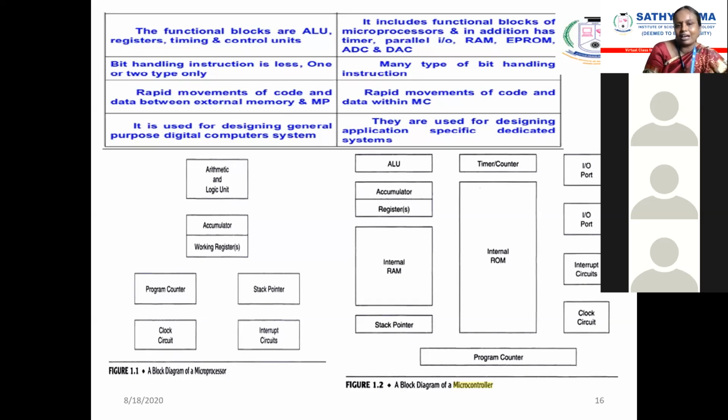For example, there are power and control circuits. In power electronics you learn that power circuit will be there and control circuit will be there. If I want to protect my control circuit, we always have some intermediate stage. That is needed. But apart from that, we don't need any interfacing IC between the microcontroller and my peripheral devices.